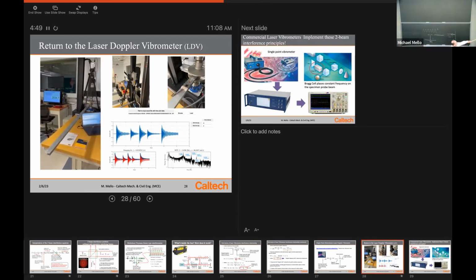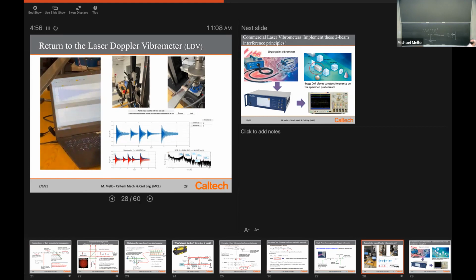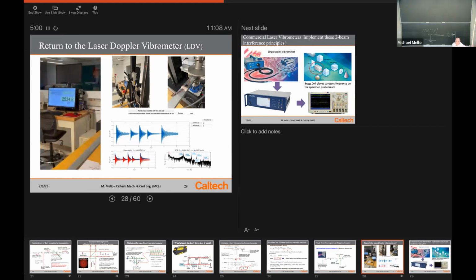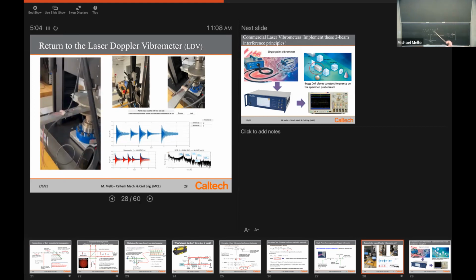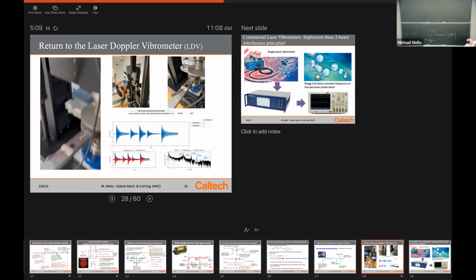There's this beam vibrating. There's a laser vibrometer pointing down, way down near the clamping position of the beam. This is an actual signal coming from the vibrometer, all processed for you in real time, okay? That's a damped signal already processed instantaneously. Here's the zoomed in view. There's the laser beam focused just behind a strain gauge that I had on the sample as well.